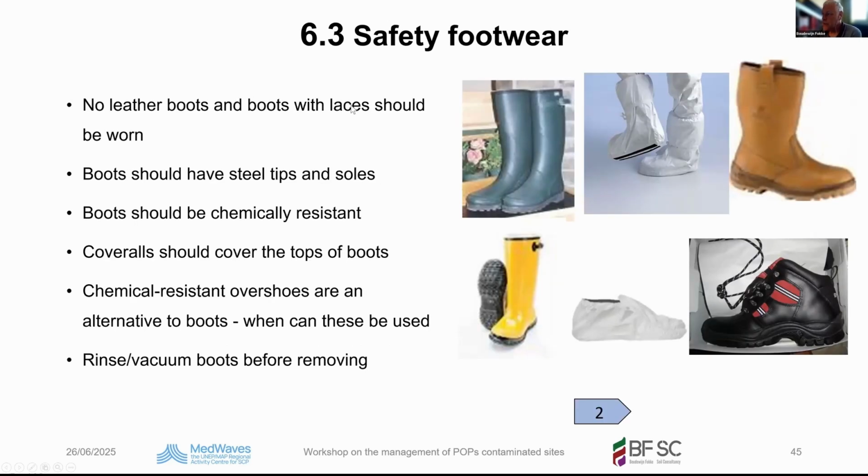We come to the safety footwear. No leather boots and boots with laces should be worn. Boots should have steel tips and soles. Boots should be chemical resistant. Coverall should cover the tops of the boots. Chemical resistant overshoes are an alternative to boots.